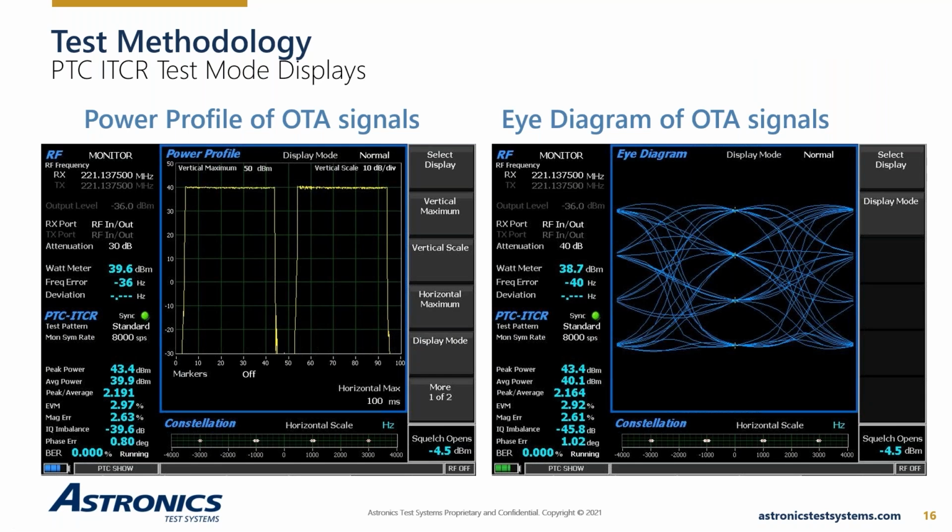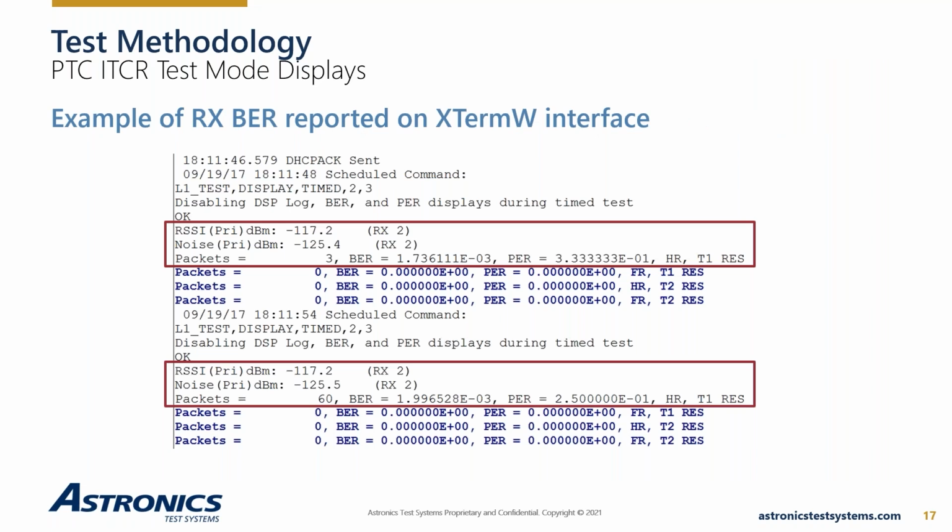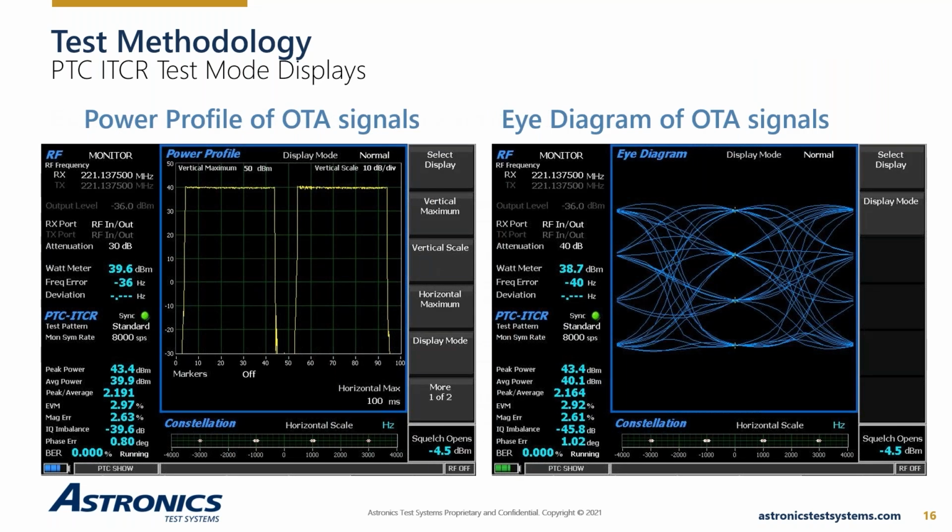And so the eye diagram, the distribution plot, and the constellation are all analogous to each other, just looking at it from a different point of view. So the eye diagram, I'm sort of looking down on top of the whole thing. The distribution plot, if I turn it up on the side, and then the constellation is when I turn the distribution to its side, I'm just looking straight down on top of that. And so that spread at the bottom is an indication of how good or how bad the system is operating. And the eye diagram helps you see that.